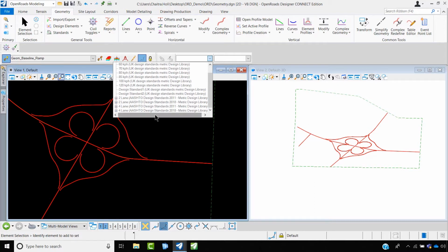So for this project, let us proceed considering it as a two-lane AASHTO project. Under this, it is again bifurcated based on the maximum superelevation to be provided and also the speed. So let me consider the 4% superelevation and the main road design speed.